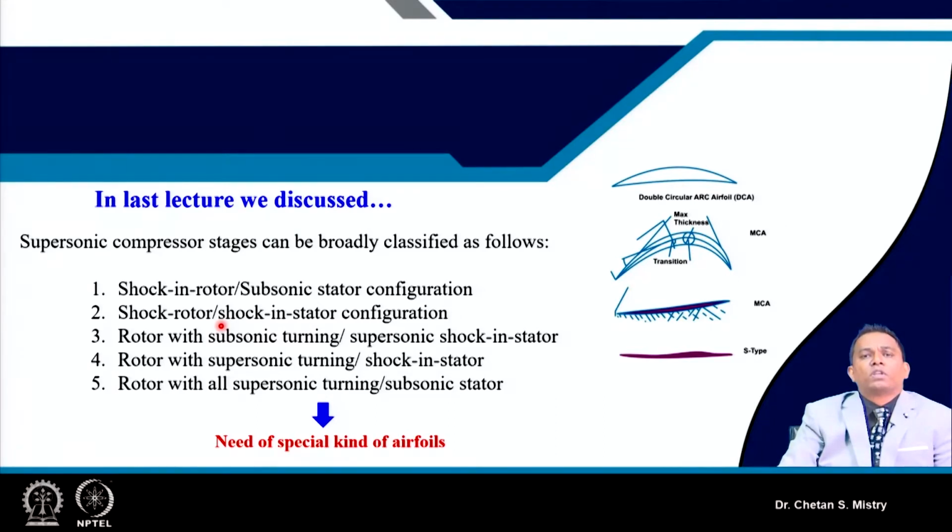A whole lot of diffusion is done in the stator, especially the whole acceleration of the flow goes inside the rotor, and at the exit our absolute velocity is going to be supersonic. When that supersonic flow strikes my stator, the stator acts like a supersonic stator, giving supersonic flow formation within, and we can call that a shock in stator.